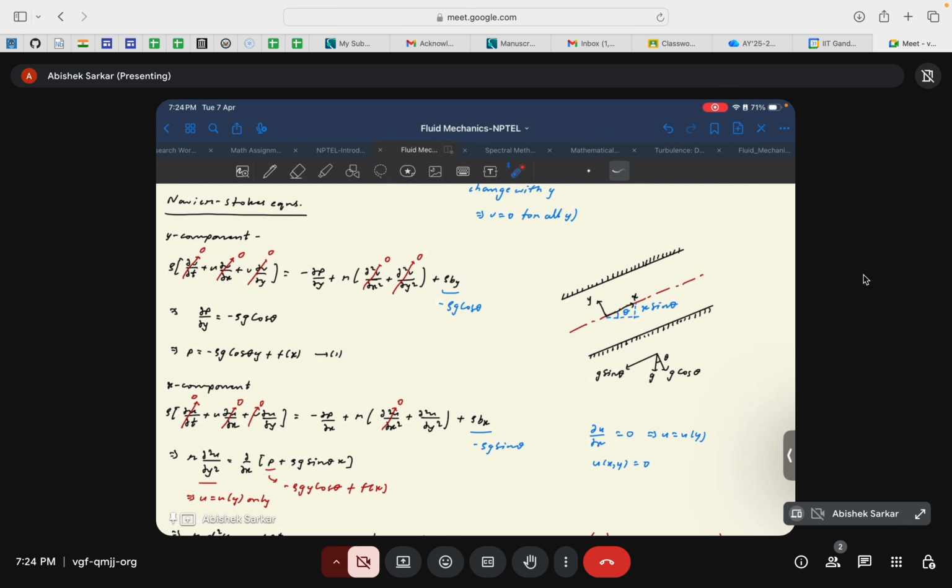for example, if your flow is along the x direction, deal with the flow along the x direction last, because you eventually see that the momentum equations from the other components, that is along the z and y components, will give you some conditions that you can impose on the x momentum equation to get the final form. Again, you can also do it the other way around, no problem at all, but it turns out to be a much cleaner way. Okay, let us see what we get.